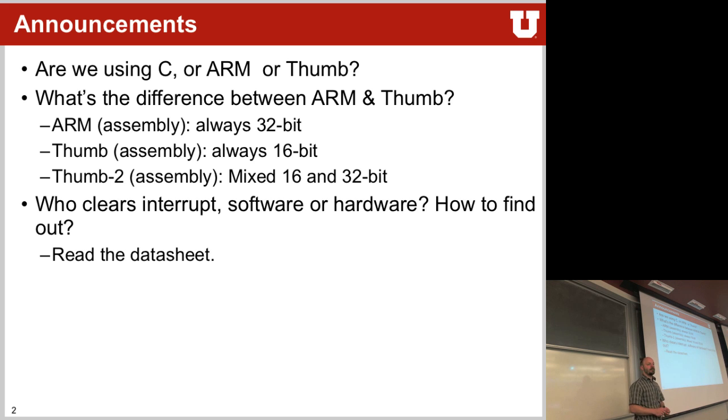Yes? So I finally found the Cortex M3 guide on ARM's site. But the Cortex M3, does it do kind of a hybrid between 1 and 2 and not do some of the 32s? Because you look at that 180-page guide. Yes. It goes over the instruction set. It doesn't include everything that's in the full Thumb 2. So it is also a subset, and it does not implement all of the different functions.